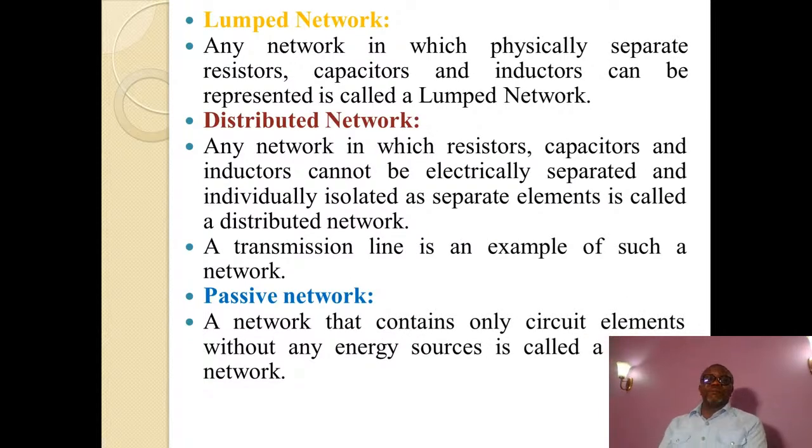Lumped network. Any network in which physically separate resistors, capacitors, and inductors, that is the circuit elements, can be represented is called a lumped network. And any network in which resistors, capacitors, and inductors cannot be electrically separated and individually isolated as separate elements is called a distributed network.